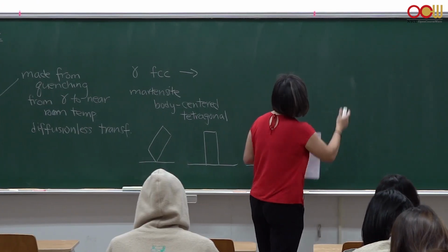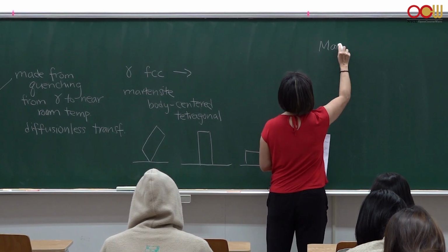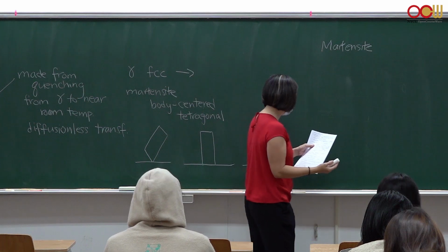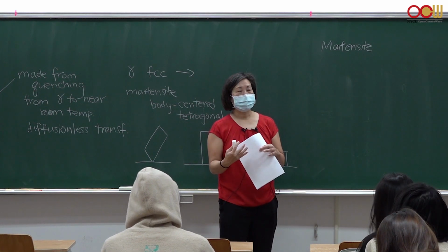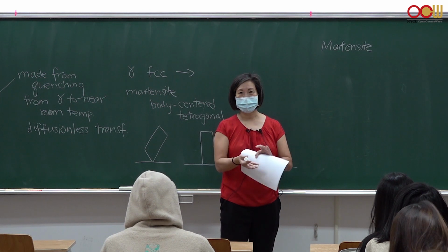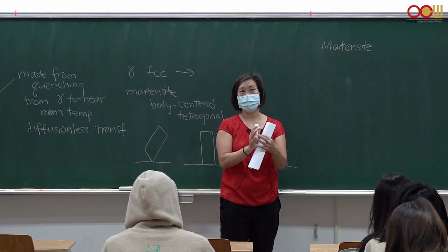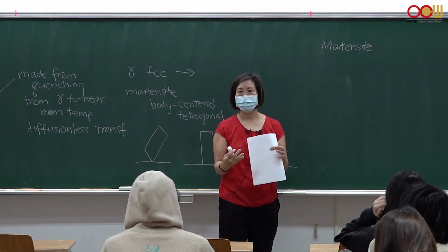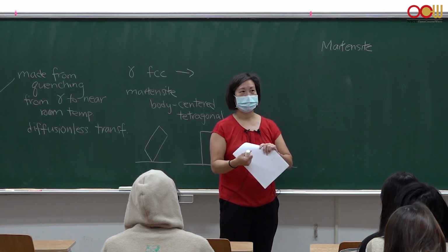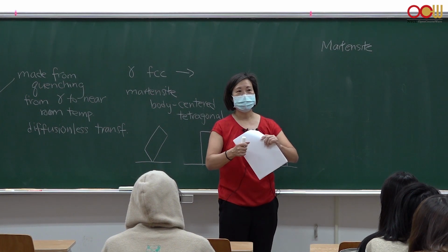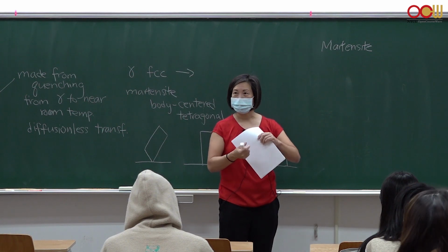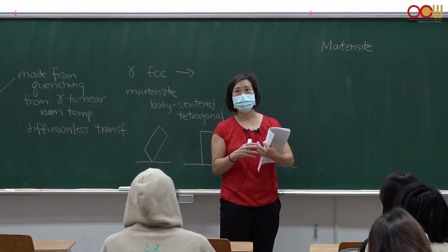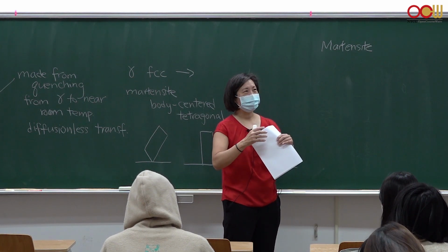So you have Martensite, and you have a crystal structure that is body-centered tetragonal. Because it's formed so quickly, it has a lot of strain. There's a lot of defects in the structure. It's definitely not the same structure all the way through, right? So it's body-centered tetragonal, but it's very disordered. And so when you bend Martensite, you can actually cause some of those distortions or the disorder to realign. So things that are disordered could move because the disorder is being reorganized.